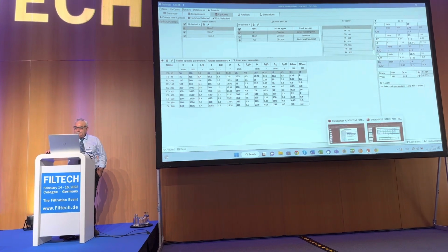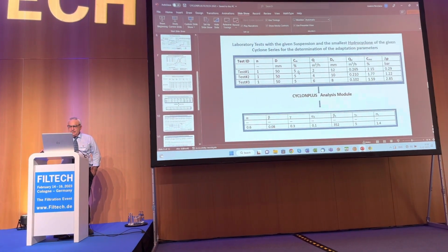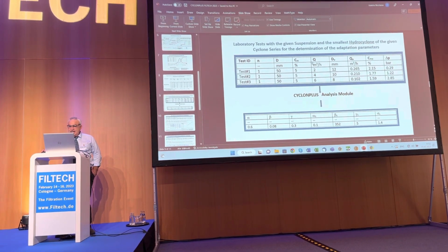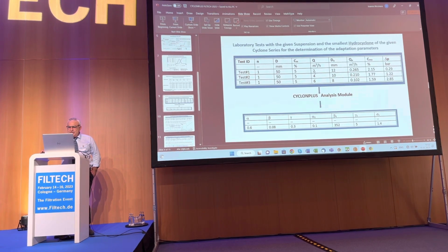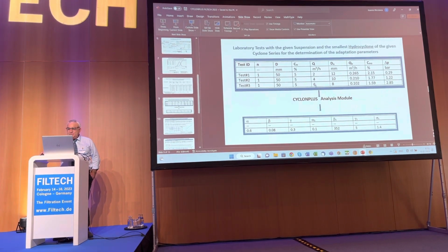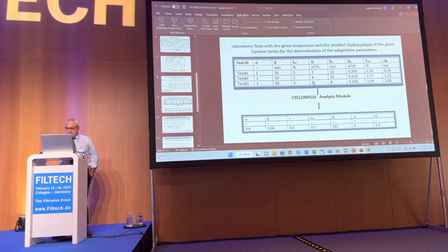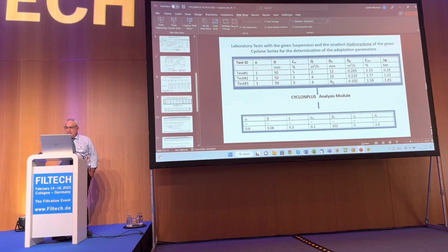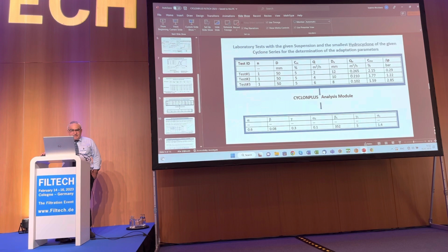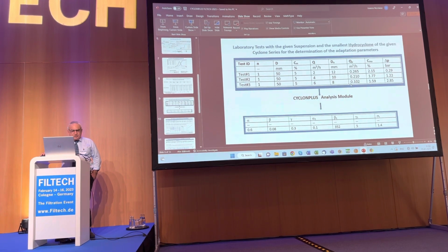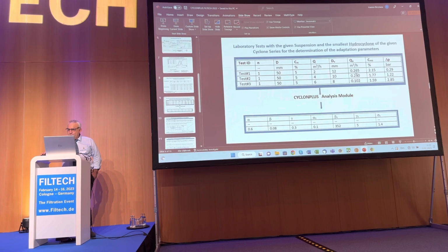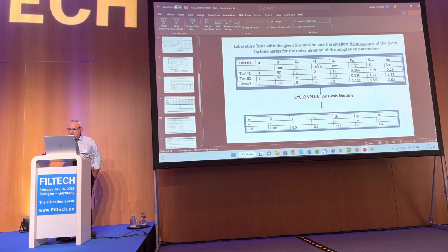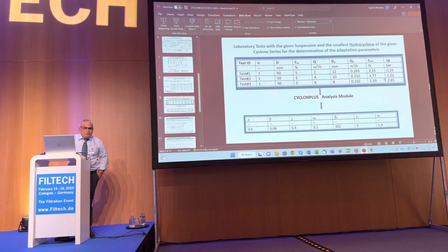And then we measure, we have 5%, that is the fit for all 3 tests the same. And then one test with 2 cubic meters per hour, the second test with 4 cubic meters per hour, and the other with 6 cubic meters per hour. The underflow diameter 12, 10, 8 millimeters, apex. The underflow flow rate, these are things that we have to measure. The underflow flow rate, and the solids mass fraction in the overflow for the 3 tests, and the pressure drop we also have to measure.